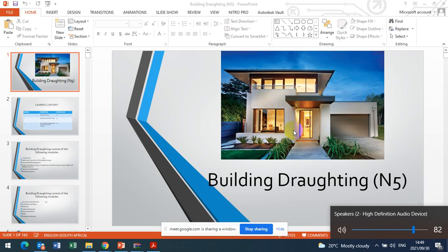So what I'm saying is I should not find you designing a house with a bedroom of 1.99. Even if it's 1.99, it's not 2 meters. It must be 2 meters and above. Those are the things we learn from the beginning, and also knowing the standard ceiling height,